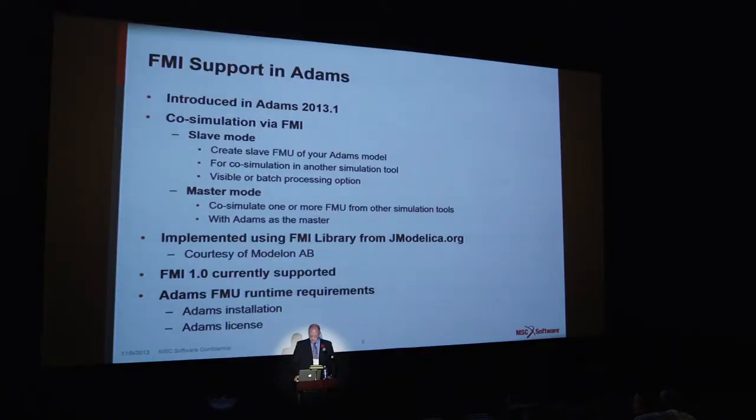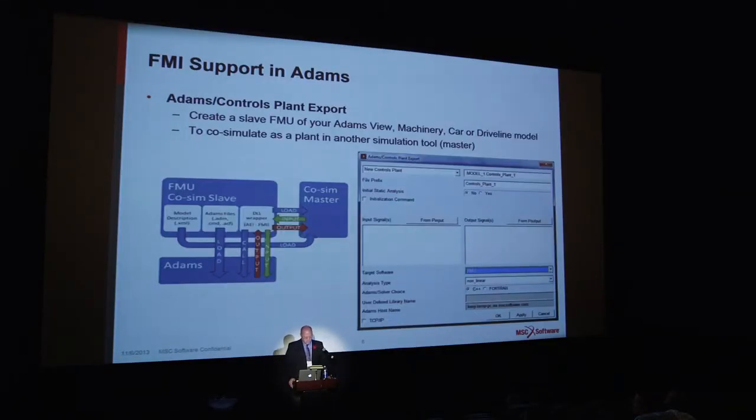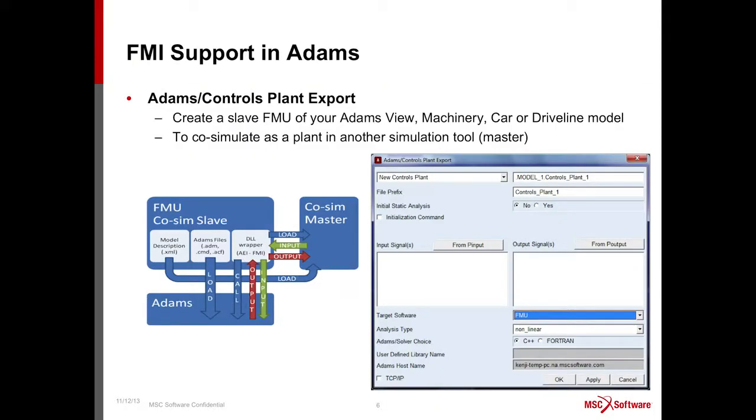So if you look at the FMI tools webpage, you'll see Adams there supporting both co-simulation modes, and it's currently marked in yellow. So we have some work to do to validate that interface with other simulation tools. Within Adams there are many products. We're using the Adams controls, which was a natural way to implement FMU support. So we basically extended that interface, Adams controls, to support FMUs.